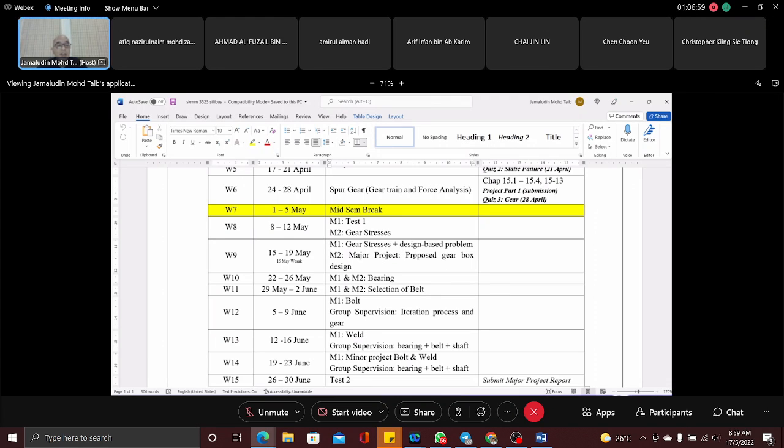Propose that schematic drawing with a bit of calculation, because it should start with the output first, because you know the output. At the end of the day, you have 2 inputs, or maybe 1 or 2. Maybe the configuration will be different. When you finalize the configuration of gear, do the calculation again. Maybe you might get a maximum load of 6,000. That's fine, because the maximum load given to you is 5,000. If your gear is 3,000, that's fine, you have enough of a safety margin.